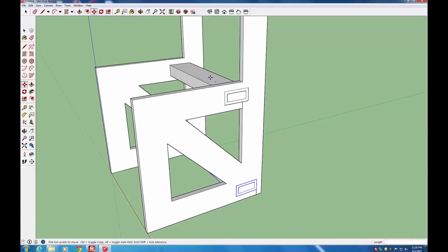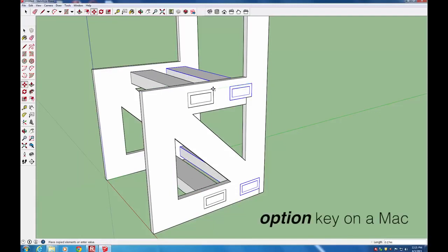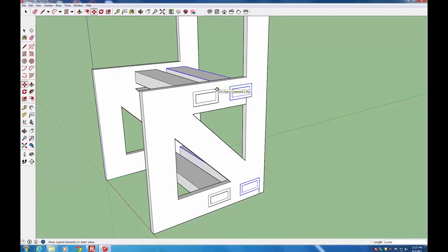So next we want to make several copies of these rectangular tubes moving forward. So we're still in the Move tool, but I'm going to go to Select tool and select both of them, just with a click and then Control, click. So now you can see that both the rectangular tubes are selected. Go back over to the Move tool, click anywhere on them, Control, click. I'm going to slide it over, making sure that we're staying flat along this face. And I'm going to move it 0.15 meters, so I type in 0.15 and enter. And I actually want to make not just one copy, but 2 copies. So then next you can just type in 2x and enter, and it'll double that.